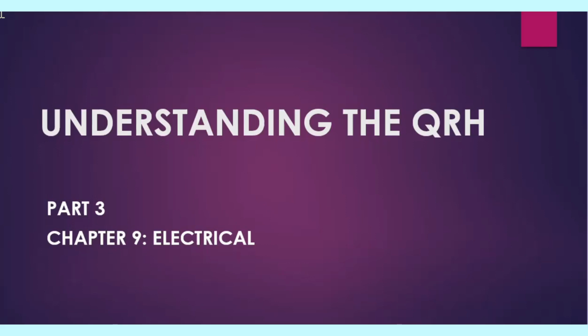You will definitely call for the QRH after you face an emergency or an urgency or a fault. You will call for the QRH if there is a memory item. Before you call for the QRH, you will execute the memory item, then you go for the QRH. Nonetheless, it doesn't mean that, okay, I just have to commit the memory items to memory, and the other things I will just get off the QRH when a situation arises. That is not the correct way of thinking.